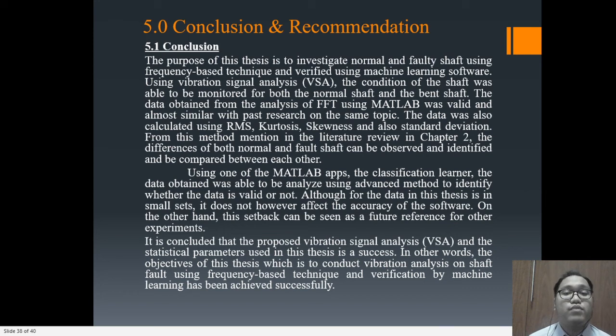The data obtained from the analysis of the FFT using MATLAB was valid and almost similar to the previous research online. The data was also calculated using RMS, kurtosis, skewness, and also standard deviation. From this method mentioned in the literature review in chapter 2, the difference of both normal and faulty shaft can be observed, identified and compared between each other.